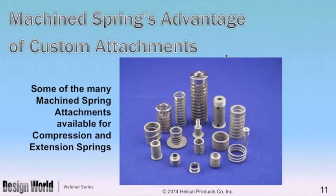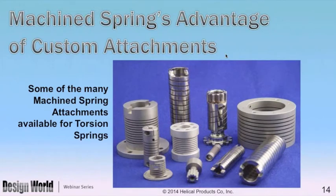Now these springs are primarily compression and extension springs. And as we go a step further and look at torsion springs, we have about the same picture, except the nature of the attachments are different. And this is one of the areas that makes particularly the torsion spring attractive. We can, with these attachments, put a pure moment on the end of the spring as opposed to a force at a distance, which becomes a moment.